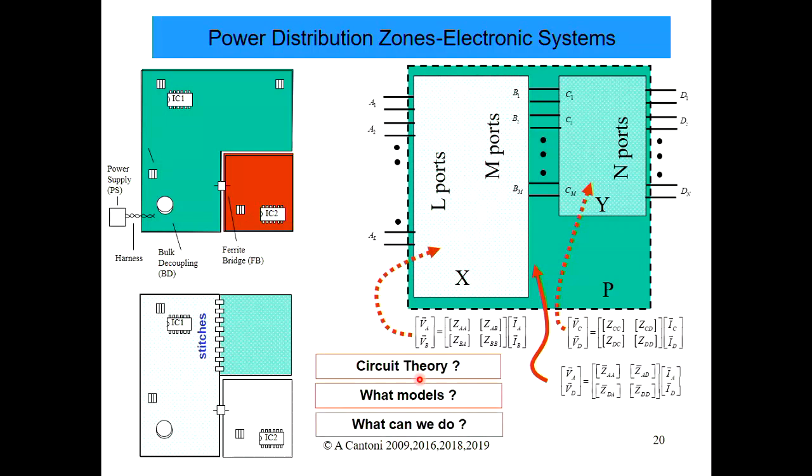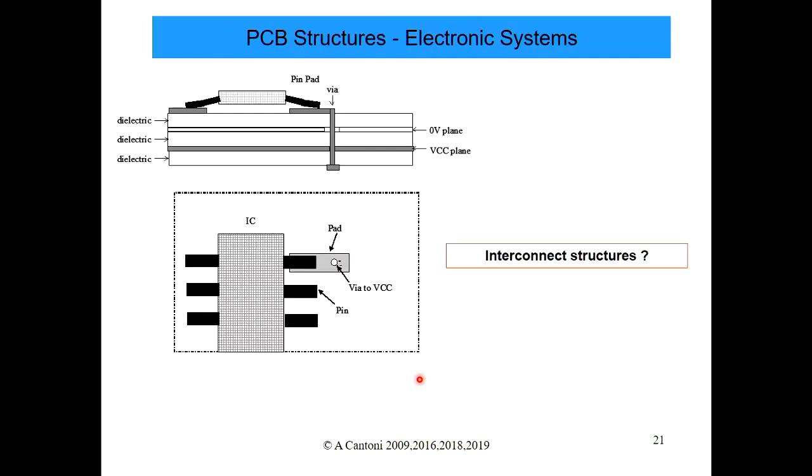So another thing that needs to be modelled, another example, where we're doing modelling, is a via. On a printed circuit board, typically you might have a ground plane, which is 0 volts, one side of the supply, but also generally the reference voltage for the signals. And you also have the power supply plane, VCC.